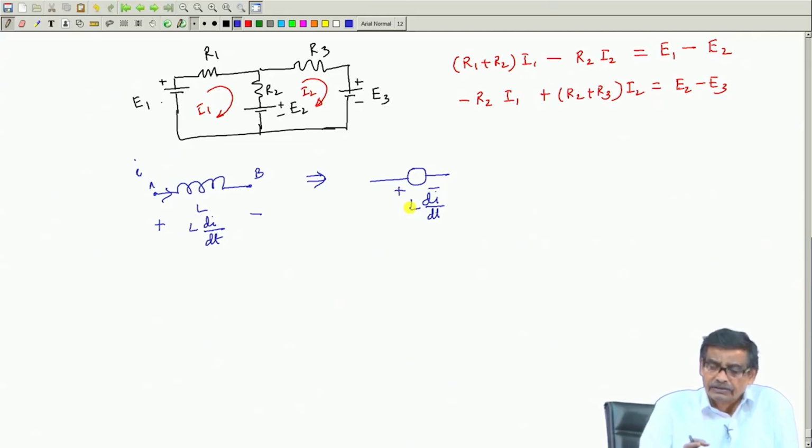Therefore, the conventional sources are batteries or grid supply voltage. But because inductance and capacitance can store energy, even without these conventional sources like battery and grid, an inductor with some initial current, that is with initial energy stored, will still be able to drive current in circuits.